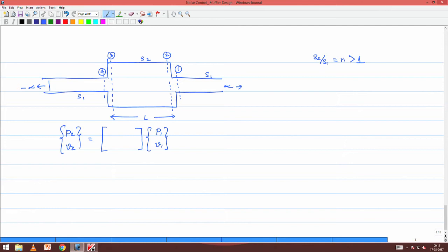Okay. So, we need to relate all the upstream and the downstream quantities with a certain matrix, because at every station there are two states, pressure and velocity. We need a relation relating the two, right. So, the equation relating P2 and P1 V1 is P2 equals P1, that is it. Okay. So, it is 1 0. Similarly, V2 is equal to V1; remember that is why we changed over from particle velocity to mass velocity. V, the mass velocity, is just the same on both sides. So, this is just an identity matrix, no big deal, right.